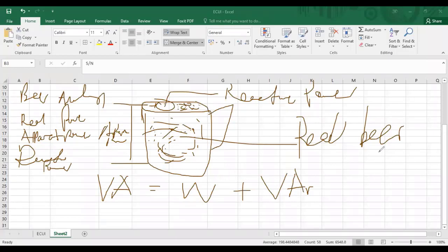This is a Pythagorean theorem, so we can have what we call the power triangle, where this side is the real wattage, this is the apparent power, and this is the reactive power.